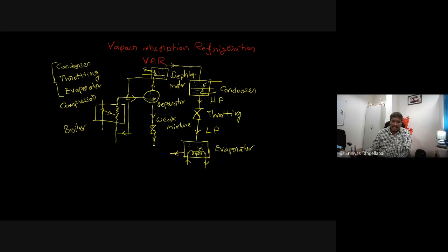After that, I am skipping some of the internal heat recovery here to explain the basic simple vapor absorption system. Then the liquid is absorbed and mixed with the vapor, or this vapor is absorbed into the liquid. Then this mixture we can easily condense into the saturated liquid condition. Without this absorption process or mixing process, we can't do the condensation.